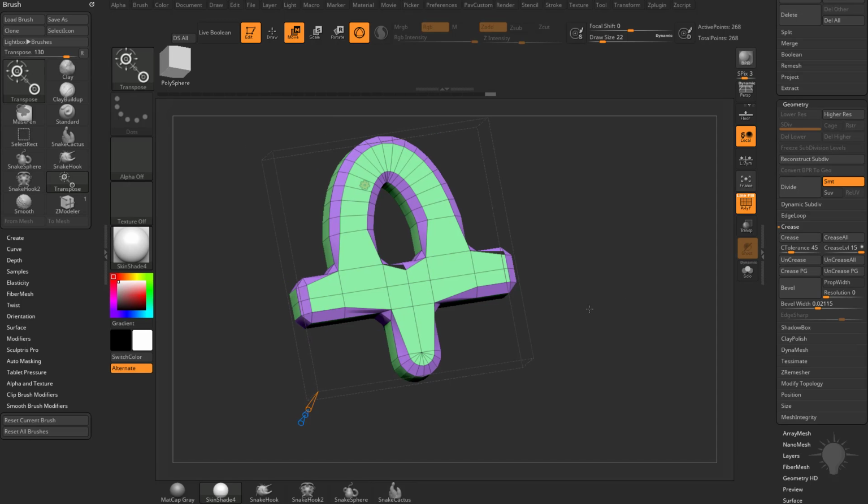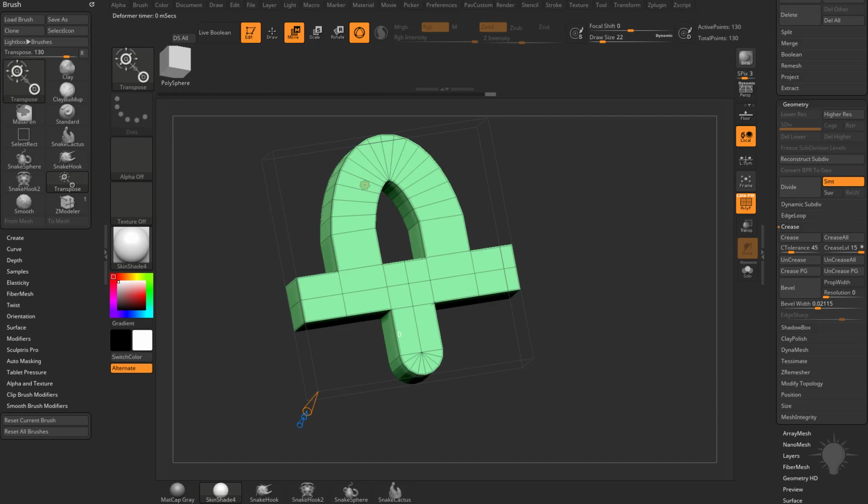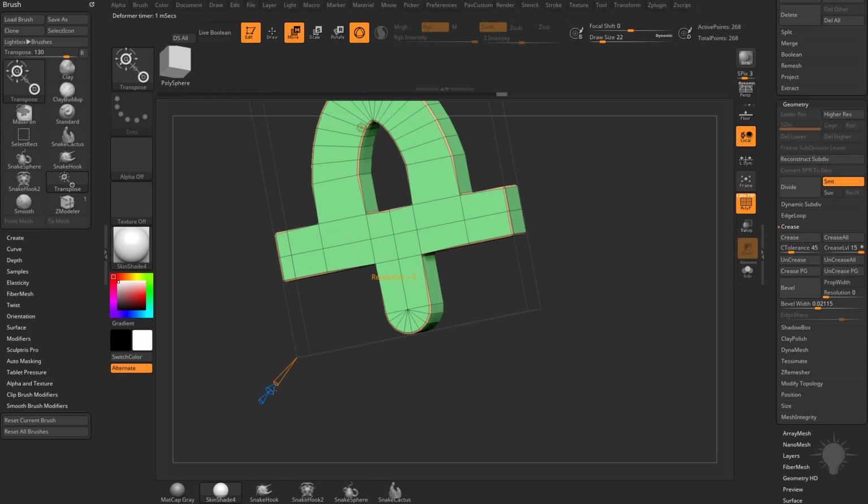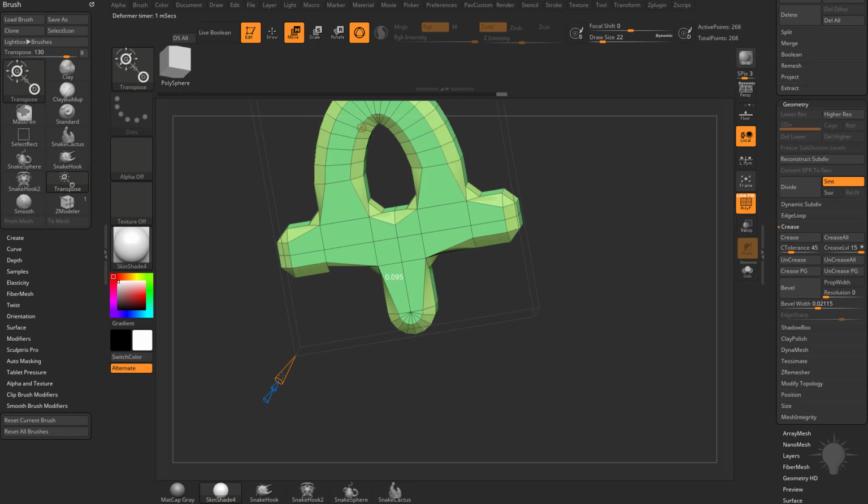Now by default, it looks like we do have a bevel value in here as 0.076. If it doesn't, then it's just going to look the same. But you're going to see we can now bevel all those same edges that we had. And the reason why it's grabbing those edges is because, here's our bevel, basically our bevel width that we were controlling earlier.